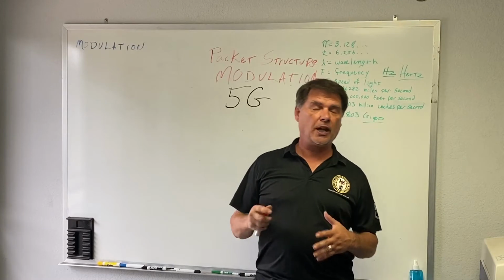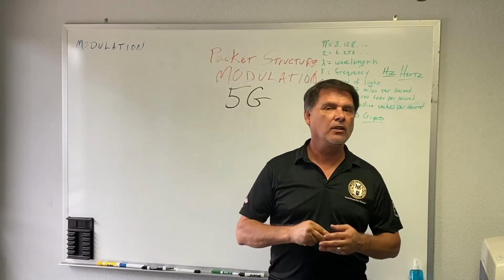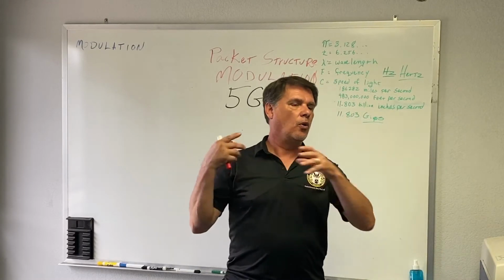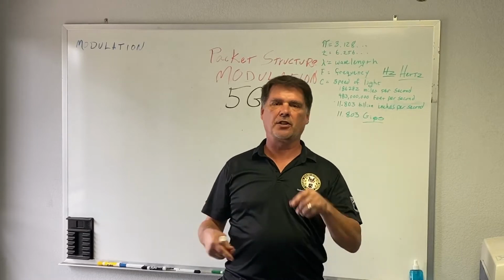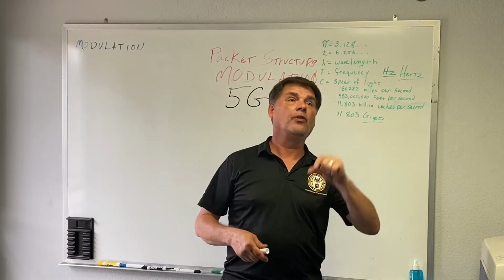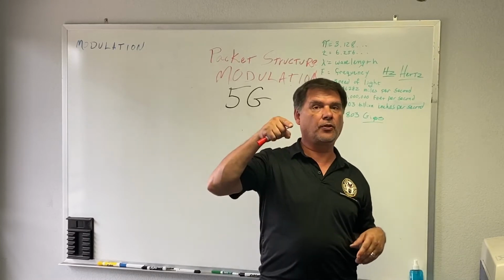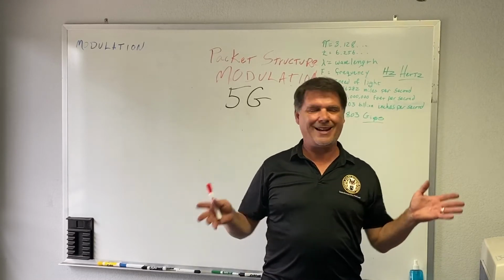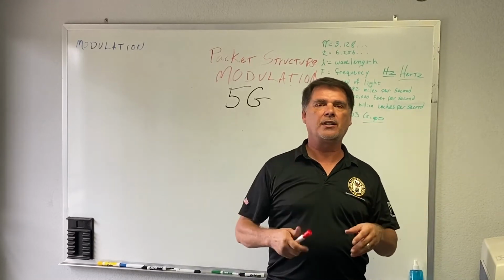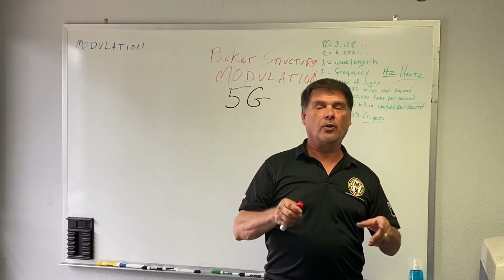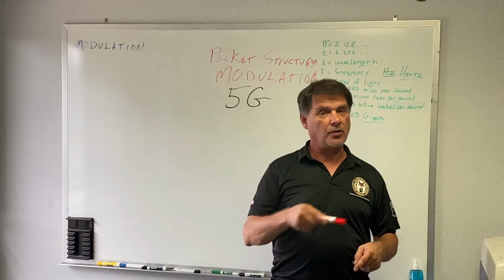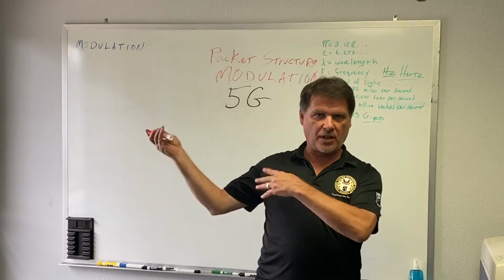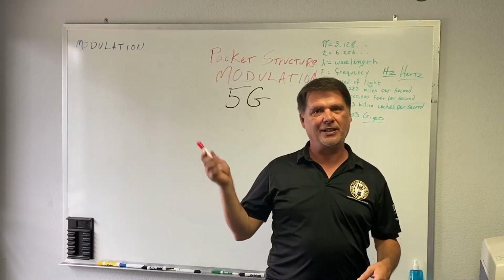Like any digital communications, Ethernet, wireless Ethernet, it has a packet structure. It needs to know what data is sent when. The data itself is just little digital ones and zeros. 0 volts, 3.2 volts. 3.2 volts is a 1, 0 volts is a 0. So all of your voice data, all of your pictures, all of your messages, those are all digitized and then run out as strings of ones and zeros. Those get put into a modulator and get modulated onto the RF carrier at whatever frequency plan they want. Within reason, obviously, the FCC kind of regulates that, as does the ITU.